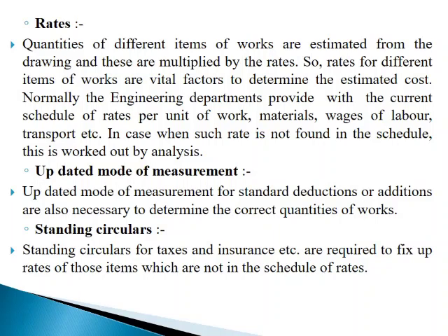When such rates are not found in the schedule, the work is ordered by the analysis of the rates or analysis of the material. Next part is the updated mode of measurement. Updated mode of measurement means the standard deductions or additions; it is also necessary to determine the correct quantities of works.